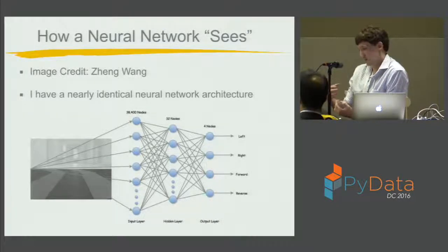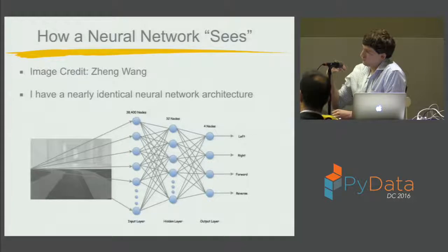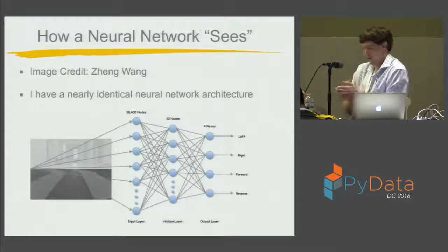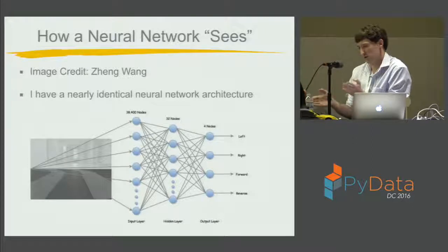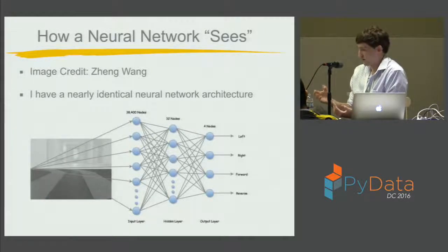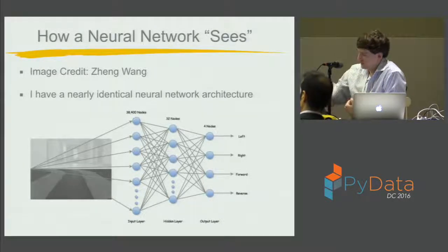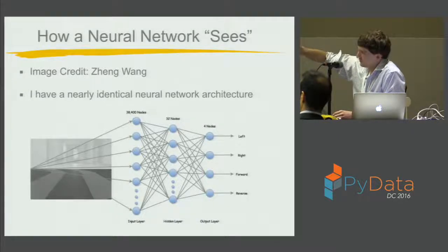I don't want to belabor this point, but this is a really important decision to make. Also, when you're training the algorithm and providing the labeled data set, especially in my case because I had a really wide track, there are cases where it could have either hugged the road, going to the left maybe, or gone straight, and either would be correct. But when I was driving, I kind of arbitrarily picked to stay in the middle or to go off to the side a little bit. So there might be 2 right answers, but the labeled data set only shows 1, and so the error rate can look really high, even though it doesn't necessarily mean that the model is performing poorly. If you had more classes and more leeway about which class was right, you might get a different error rate. So it's a really important consideration if you're thinking about the machine learning behind this for your own project; you'll spend a lot of time thinking about this problem.